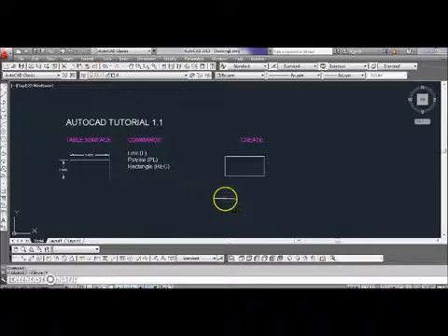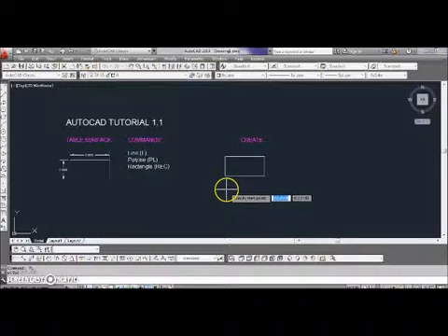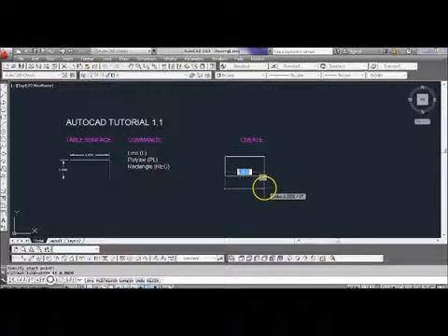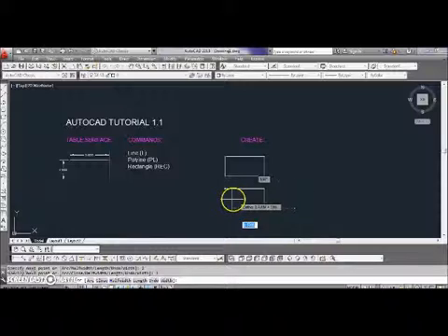Okay, we move to the second command that is called polyline. The difference from line to polyline is that we're going to make a shape with all the lines united. So we ask AutoCAD for the command PL for polyline, PL, enter, and we repeat the same process. We start with a first point, then move the mouse to the right and enter the distance that we want to use, 2, enter, and move the mouse downward, 1, enter,